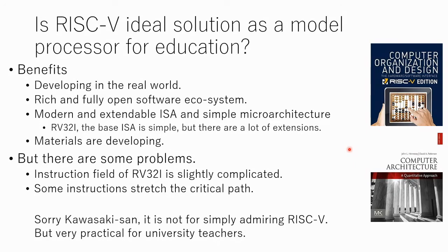Okay, but there are some problems. First, the instruction field of RV32I is slightly complicated. And some instructions of RV32I may stretch the critical path. Well, sorry, Kao-san. My presentation is not for simply admiring RISC-V.